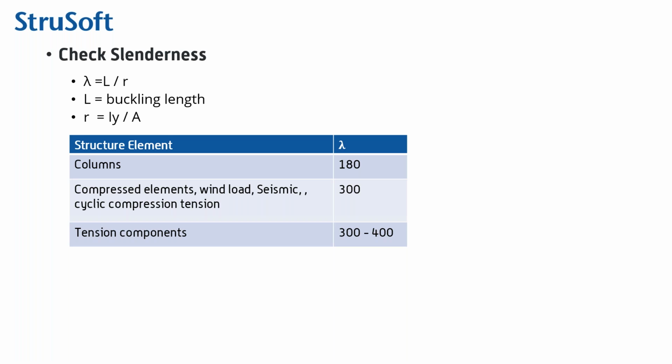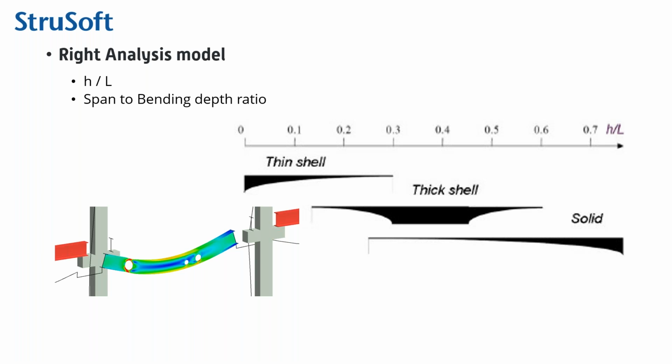Especially if you have really slender braces and columns, the problem is that they are really sensitive to lateral loads and vibrations and cyclic loading. So in all dimensioning standards there are slenderness limits, but in Eurocode there are not. But anyway, if you stick to these limits, it's always a good idea, because you have avoided many problems.